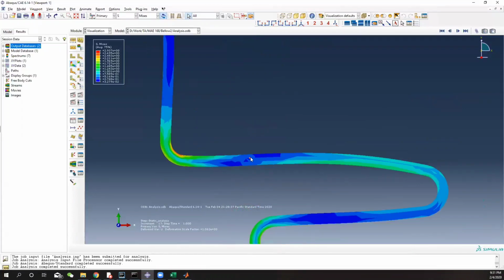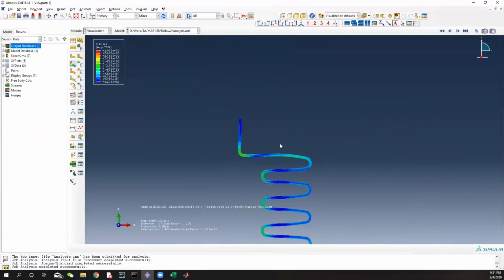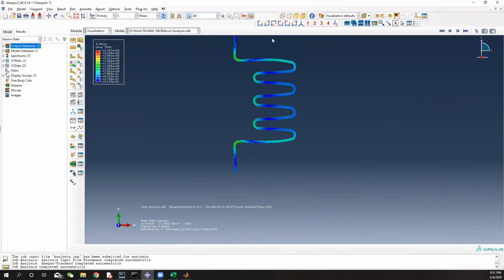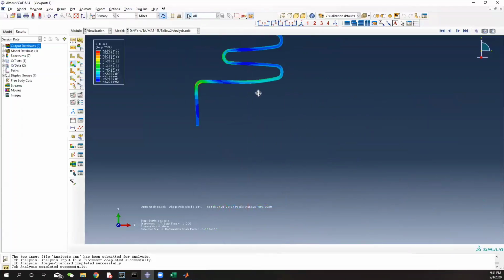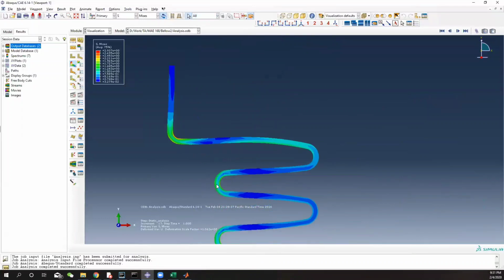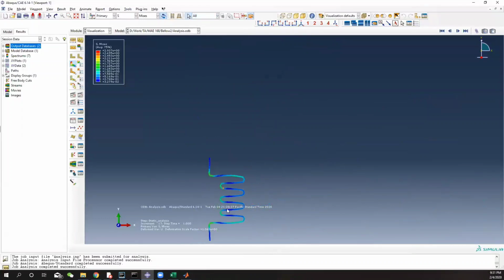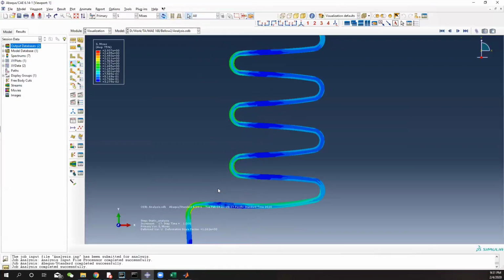because our cohesive is applied, it doesn't really change too much. If you really want to say what is different, you can see the inner surface, the stress is not as large as what is shown here for 1 layer. That means the cohesive layer, cohesive attachment cannot fully transmit the stress.